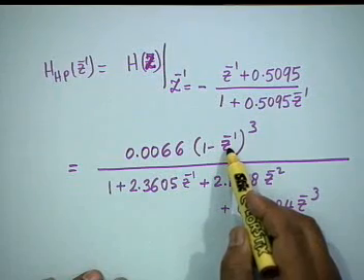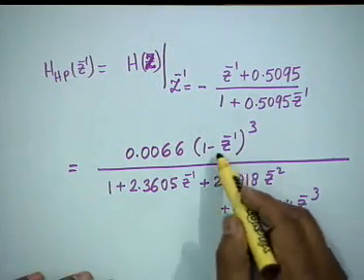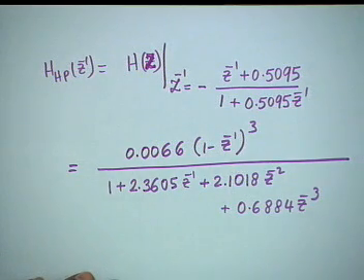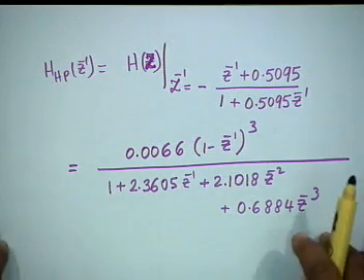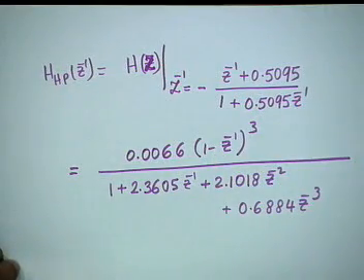One is, is this a high pass filter? It is. Is it indeed a high pass? Yes, it is, because at z equal to 1, it is 0. Now, how does (1 minus z inverse) whole cubed come? You see our numerator was (1 plus capital Z inverse) whole cubed. How did this convert to this? This is also interesting.